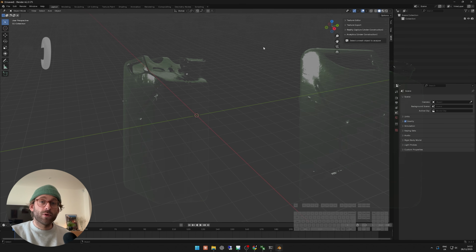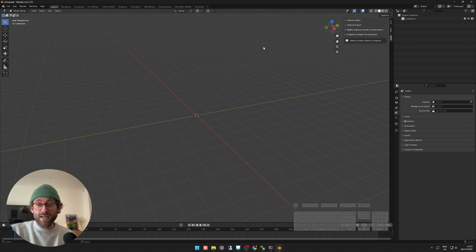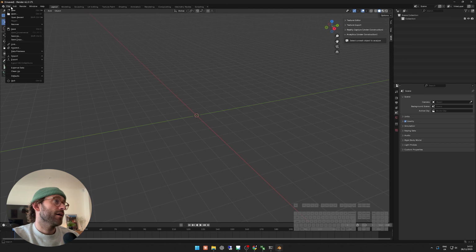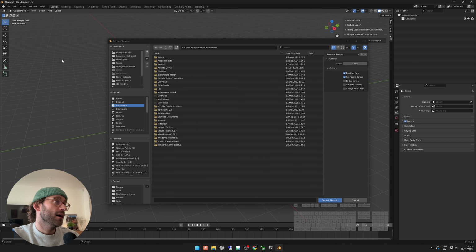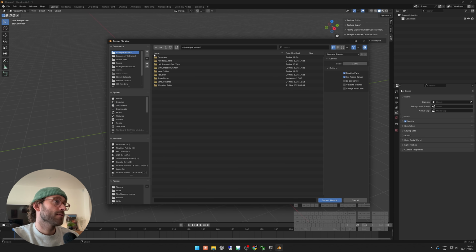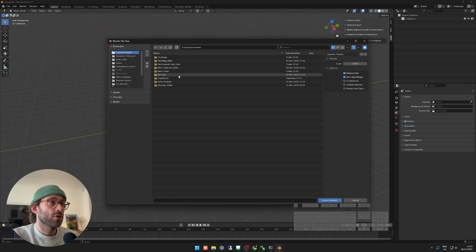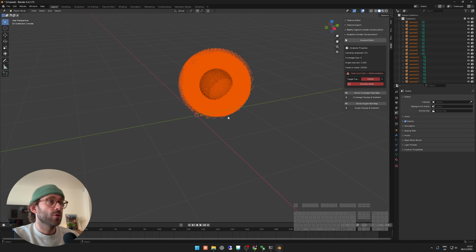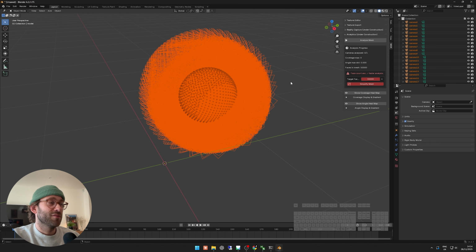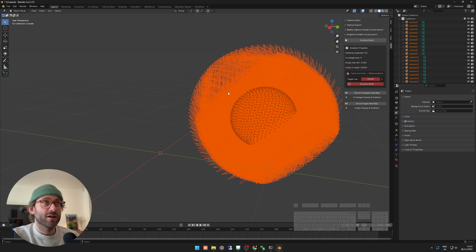And we'll want to import an Alembic file to make sure it actually has a mesh and to make sure it has cameras. So we can go over to File, Import Alembic, have some example objects here. We'll pick something, so we'll grab our red box and we'll click Import Mesh. And what that has done is it's not only imported the mesh, but it's now also imported all of the cameras. The first thing you'll notice is it's a little bit crazy, this scene right now.